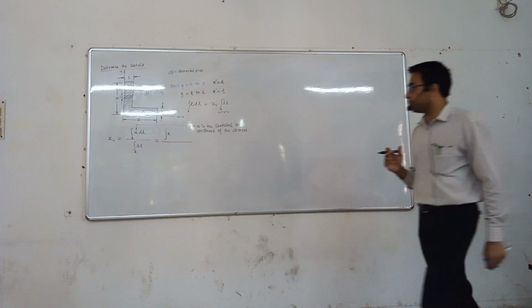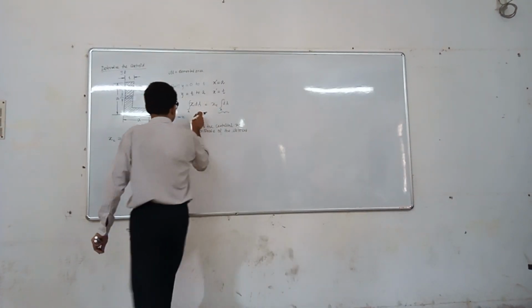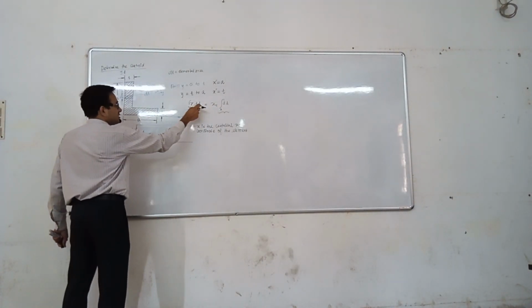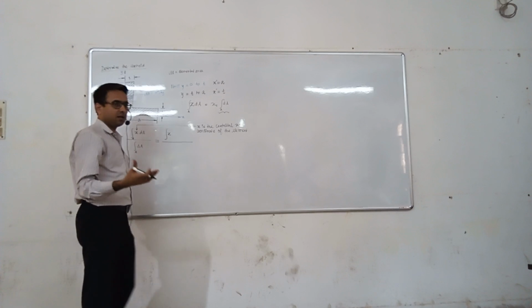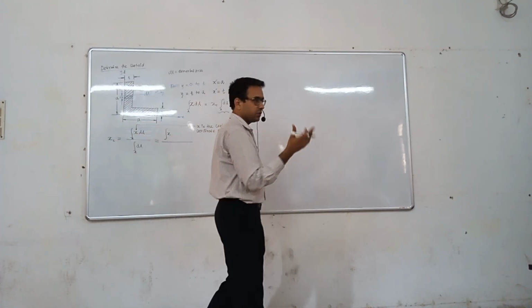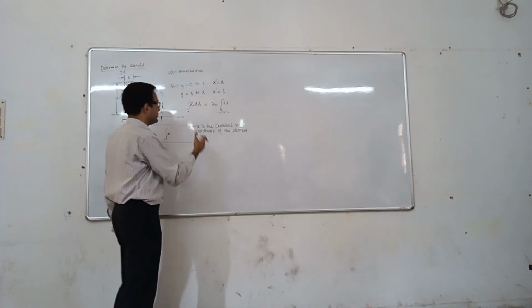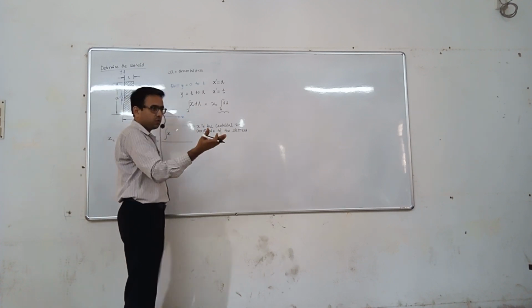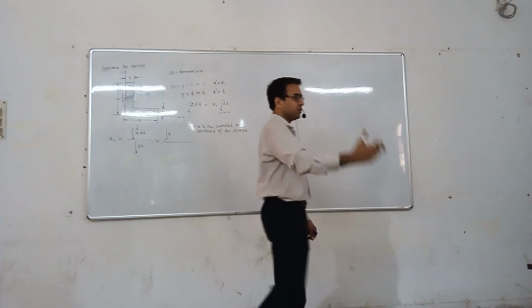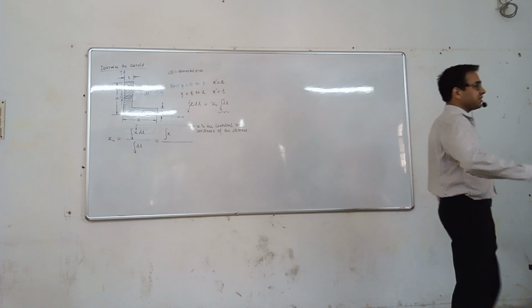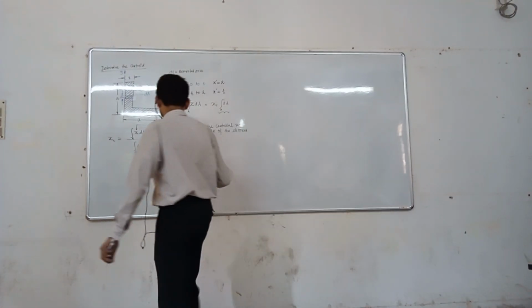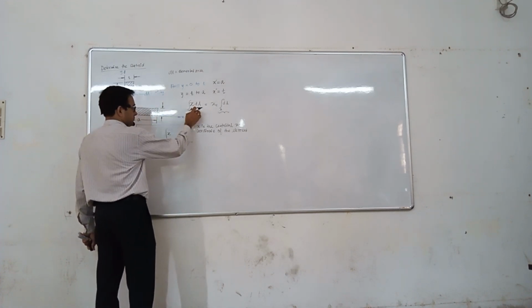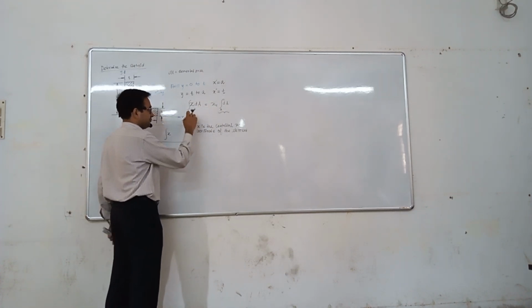So this is called the moment of area, because this is the area and this is the length, which is the arm of the moment. We have learned moment of a force, so it is kind of moment of area. We call it first moment of area. Then we have second moment of area, which we call moment of inertia in general, right? So is the logic clear?